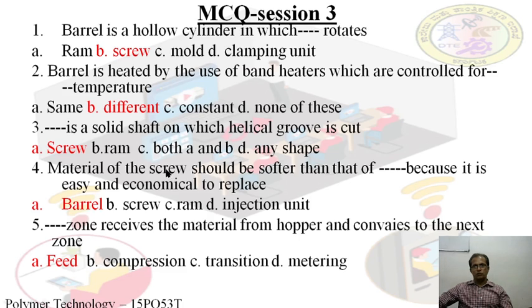So the screw finish, screw design, the L/D ratio, the depth, land, all these are very important. Hence, we cannot replace the screw easily. That will be much costlier. And the barrel, of course, we can replace because compared to the screw, barrel is cheaper, easy to design and easy to dismantle, so barrel is the most appropriate answer to question number 4.